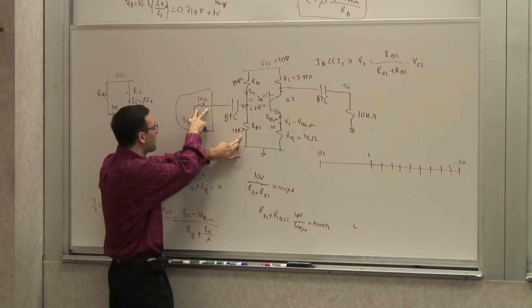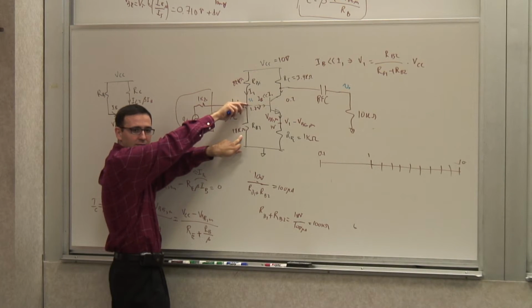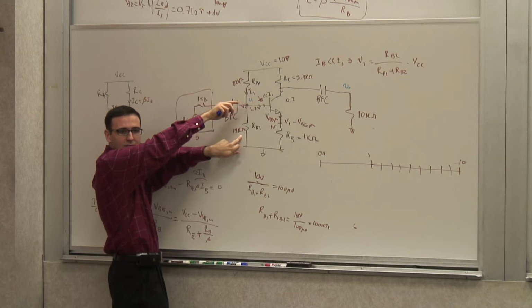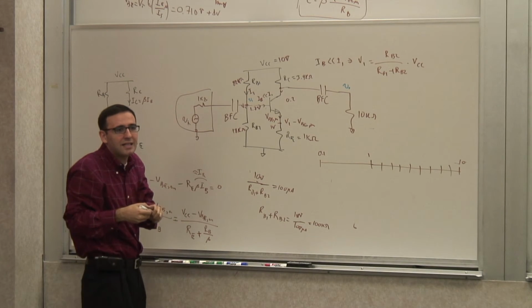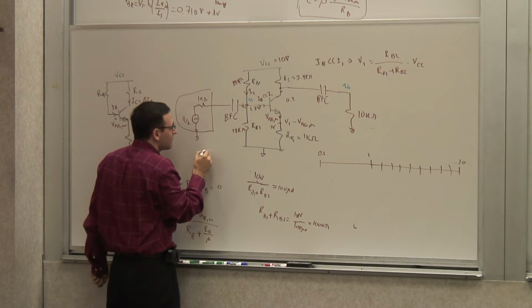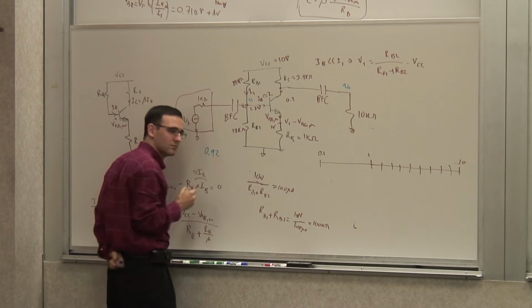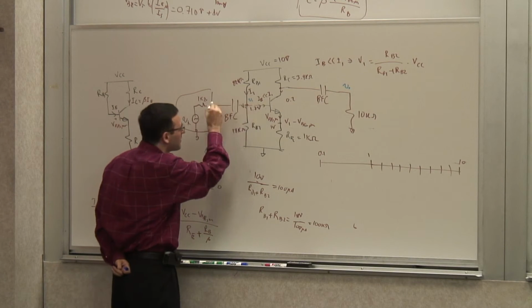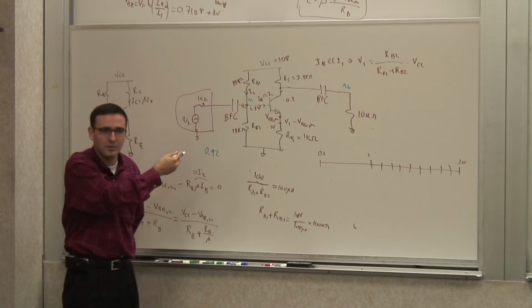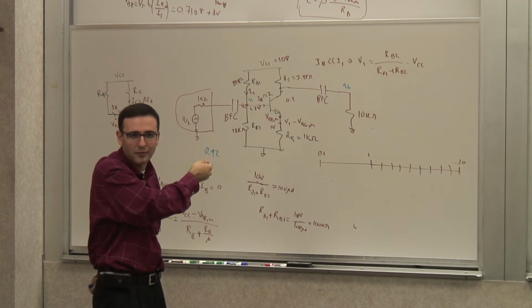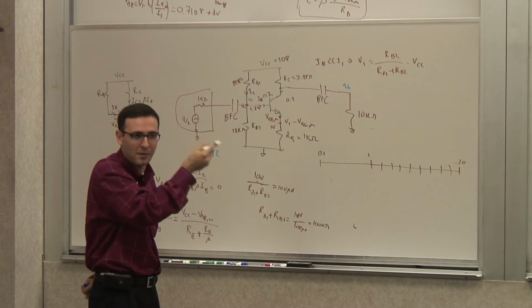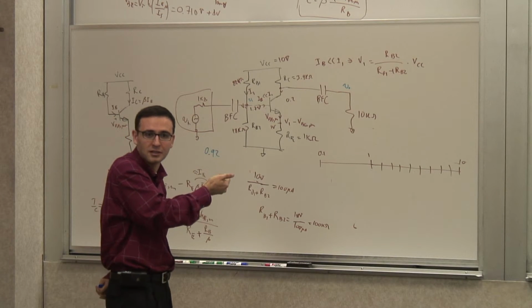So it's a voltage divider between 1K and 13K. So that's 13 over 14, probably something like 0.92. So I know the gain from here to there is about 0.92. Maybe wrong, so we'll see how off it was. I don't remember what the numbers are for this example.